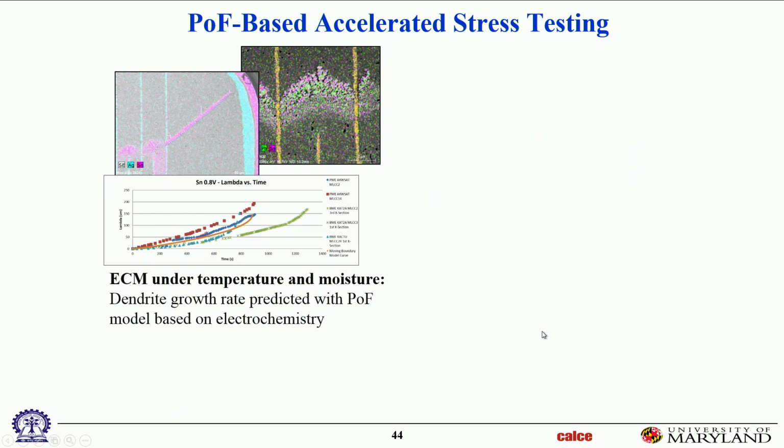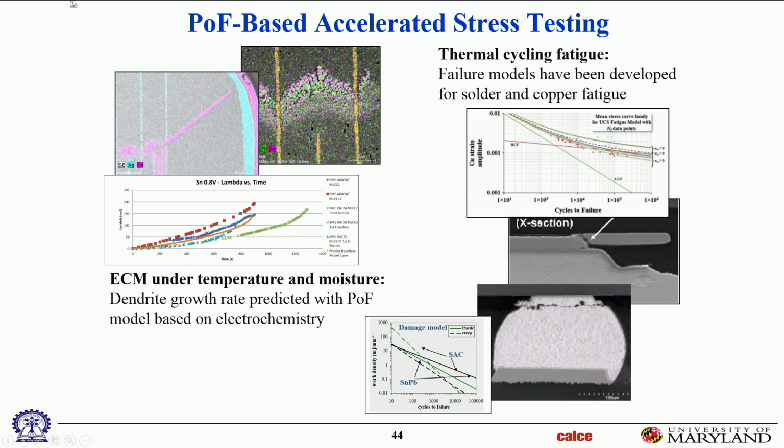Okay, so here are some examples of accelerated testing we do in the lab. I talked about capacitors growing filaments. We grow those routinely in an accelerated manner. We have models that can predict how they'll accelerate. That solid line you're seeing is our model, so our model can predict what's going to happen.